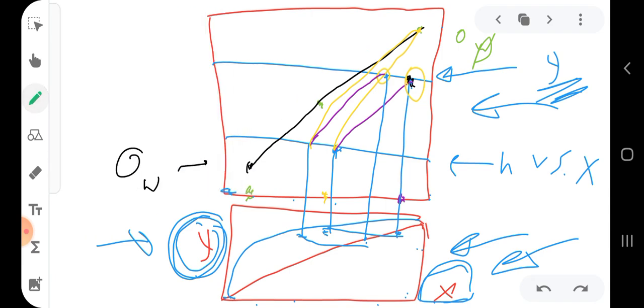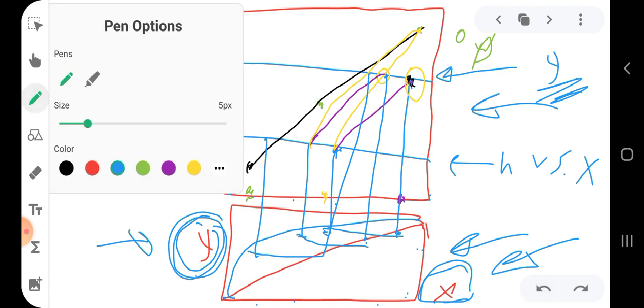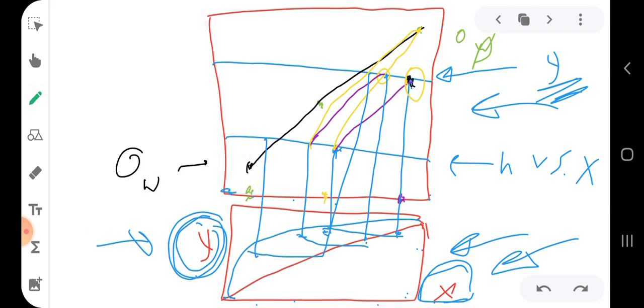I start here from the point of intersection, go to the 45-degree line, go to the equilibrium curve, and then go back to the liquid curve, and then connect the starting point here with the end point here again. And let me do it in the purple color, so I connect them again.